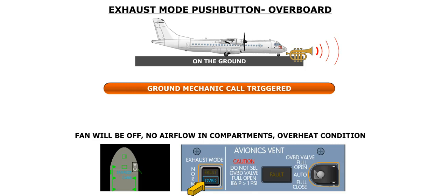If the condition levers are not in feather or fuel shut off, an amber air ventilation exhaust message will be displayed on the EWD, and an exhaust overboard label is displayed on the MFD cabin page.